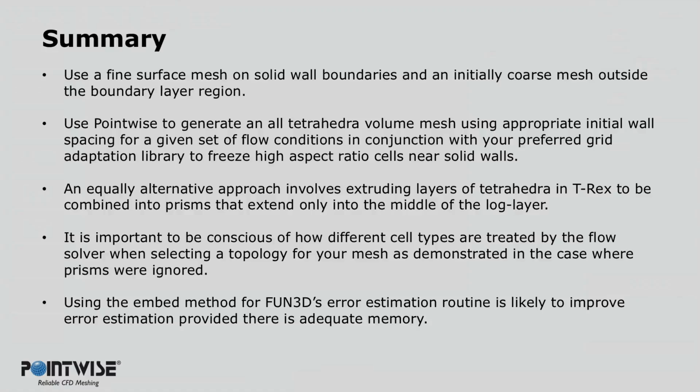To this recommendation, I would also add that for best results, one might consider increasing the surface resolution of the initial mesh since the grid points there are frozen, and then utilize a coarse inviscid grid outside of the boundary layer grid since it will be refined.